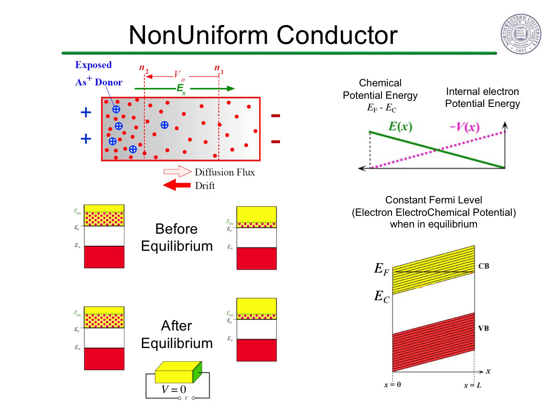This is because the Fermi level represents the total electrochemical potential, the sum of the electric potential, which increases, and the chemical potential, represented by Fermi level minus the conduction band edge, which exactly decreases to compensate. Because the Fermi level is the same, there would be no external voltage measured by a voltmeter across this material. The electric field produced is said to be entirely internal.